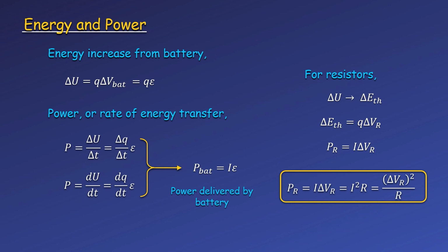I do want to focus on two of these formulas really quick, starting with the current squared times the resistance. This formula doesn't have the voltage across the resistor, which may change depending on the source voltage of the battery. This tells us the power, or rate of thermal energy transferred, is proportional to the current squared. Thermal energy is another way of saying heat, and this means if we double the current through a resistor or some other object that has resistance, the rate of heat dissipation is quadrupled. This is one of the main reasons we said we want to use resistors to limit current in circuits, because they get hot and can cause unwanted fires.